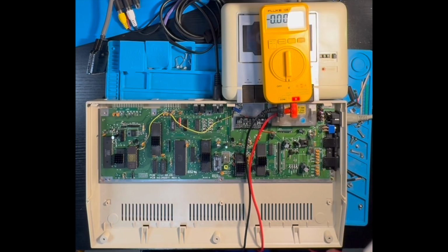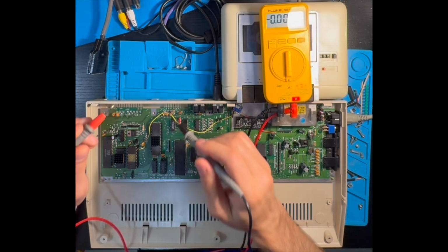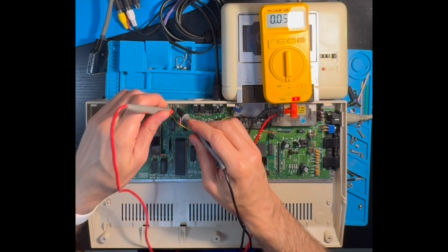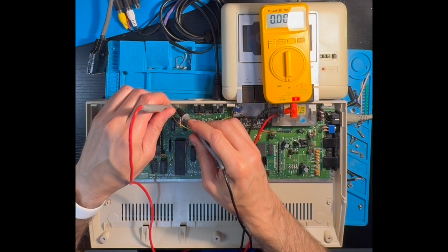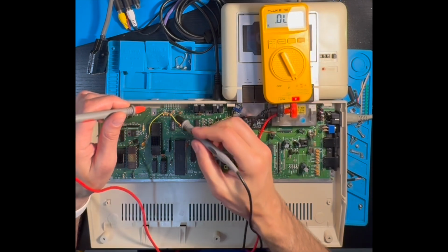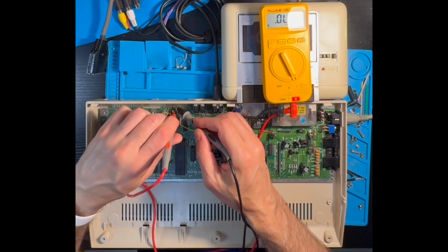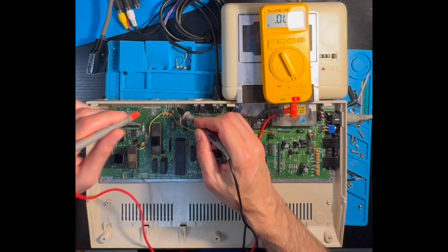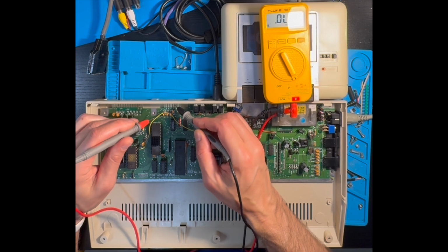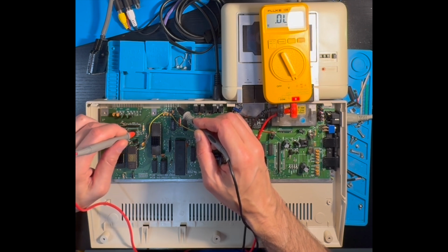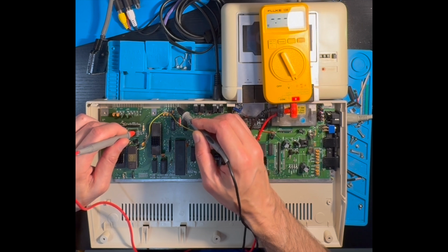So next I'm going to look to see, okay, coming from that cassette port right there, is it actually connected? Is there a short somewhere, something going on? Let me look through. And I can see it's good on that side. It's coming through. It goes through that resistor to that power regulator there, the voltage regulator.